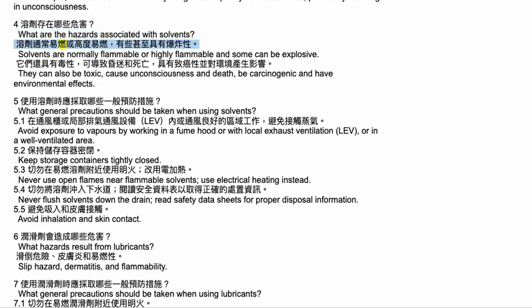4. What are the hazards associated with solvents? Solvents are normally flammable or highly flammable, and some can be explosive. They can also be toxic, cause unconsciousness and death, be carcinogenic, and have environmental effects. 5. What general precautions should be taken when using solvents?